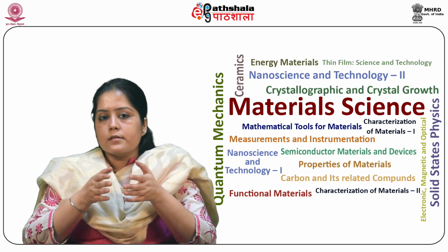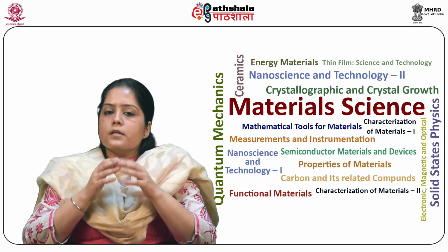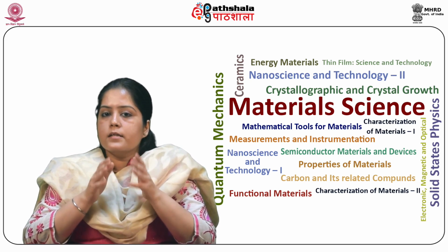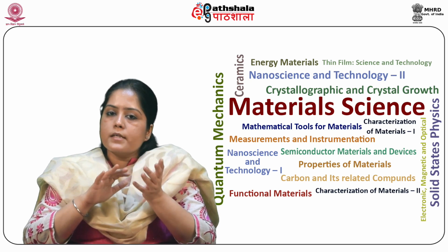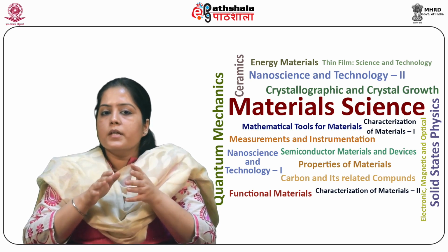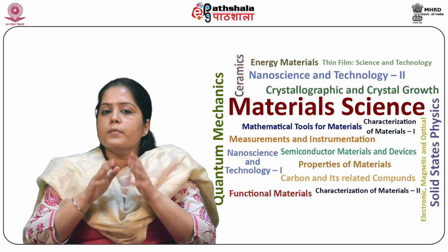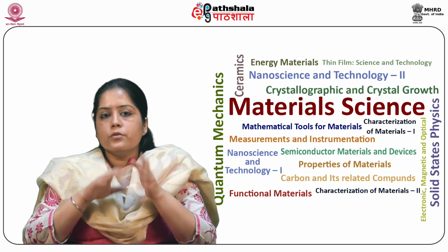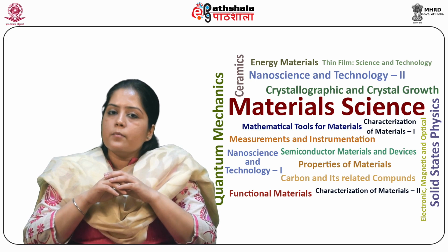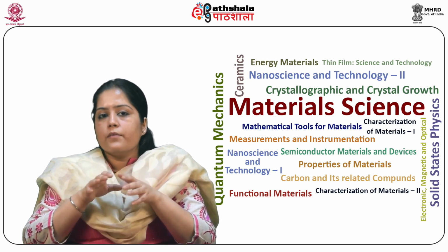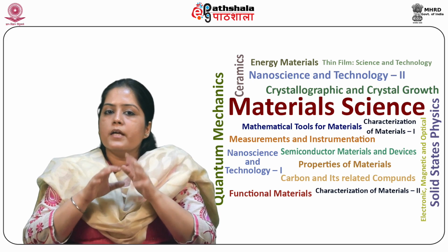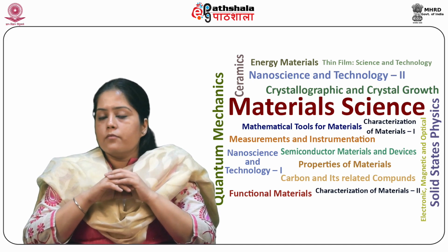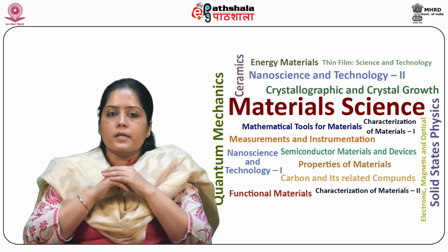The efficiency for the homojunction is around 23.3%. For aluminium gallium arsenide silicon, it is around 26.9%. Aluminium gallium arsenide gallium antimonide, that is a tandem structure, is around 32.6%. Gallium arsenide indium gallium phosphide stacked indium gallium arsenide is 30%, and indium gallium phosphide is around 33%.